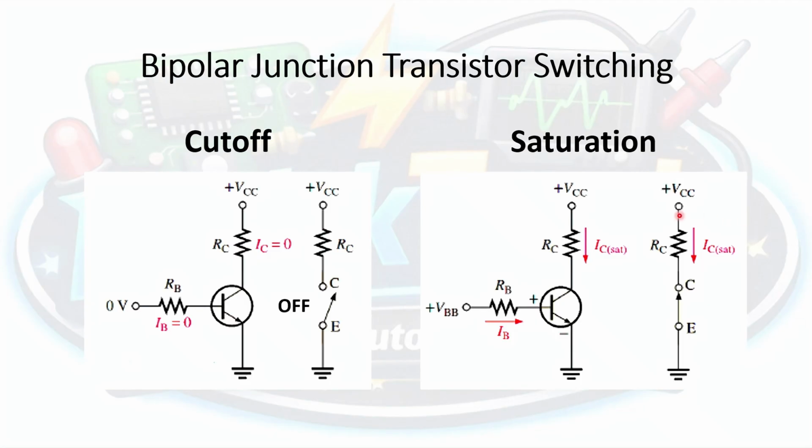Now, what does that saturation mean? Typical operation of transistors would be as follows. A base voltage produces a base current, and this base current gets amplified to a much larger collector current. If the base current goes up, the collector current also goes up by a factor equal to the amplification factor of the transistor, which depends on the type of the transistor.